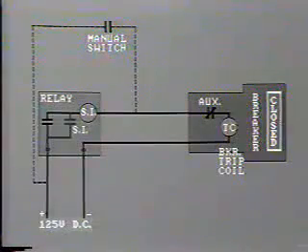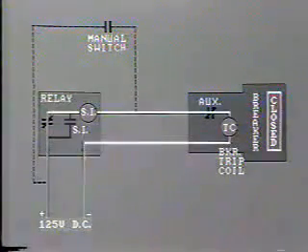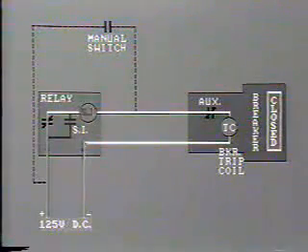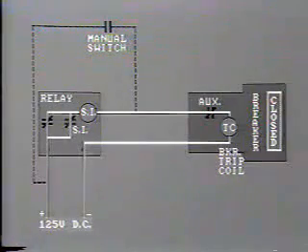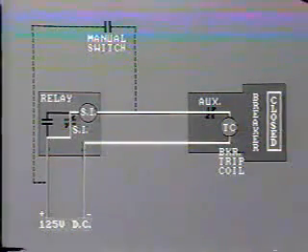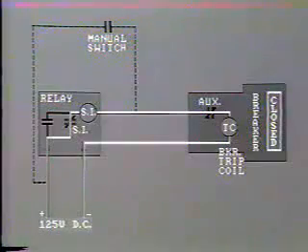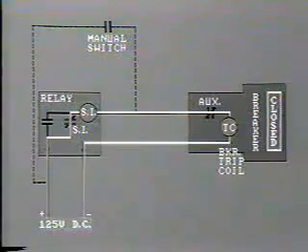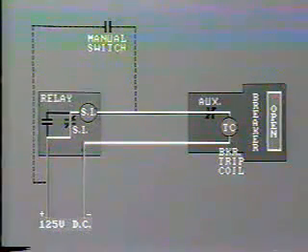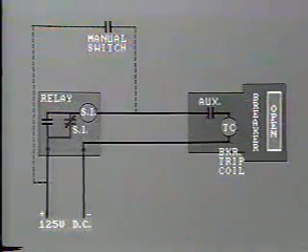It functions like this. When the tripping circuit is energized, the seal-in contactor switch is also energized by the passage of current. This in turn closes the seal-in contacts here, and they will remain closed as long as the circuit remains energized. Now, if the relay contacts open first, they will not interrupt the tripping current, as the closed seal-in contacts provide an alternative path. Only when the breaker auxiliary contact opens will the circuit be de-energized and the seal-in contact also opened.